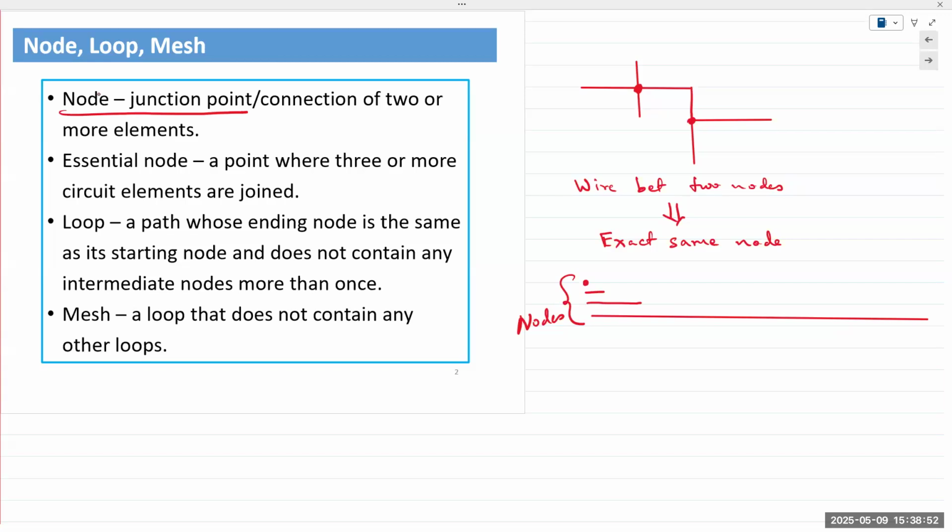So it's the exact same node, right? Does that make sense? Now, however, if you plug in a 1,000-foot long cable, or maybe even thousands of feet, now that cable would have some resistance. So instead of 120 volts, you might obtain perhaps 100 volts. There is a voltage drop across thousands of feet.